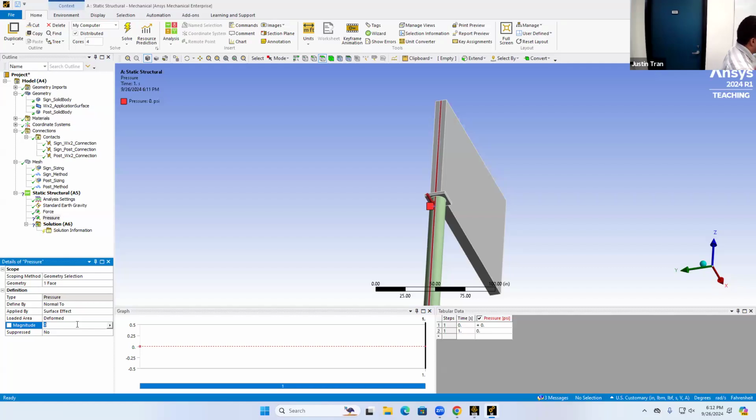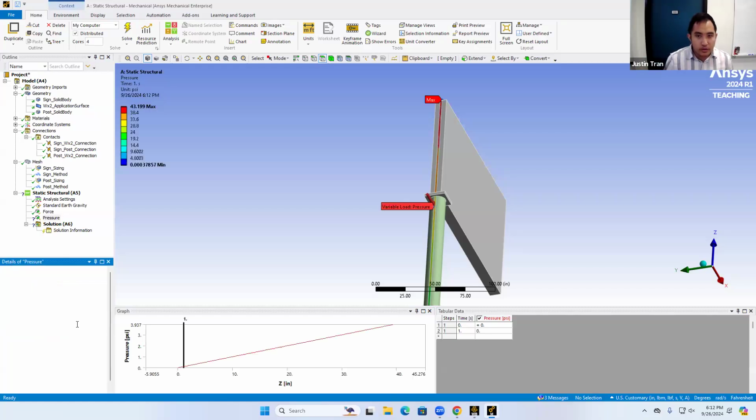To specify a spatially varying force into one of the boundary conditions here, you're going to use basically the same notation that you use to specify a formula in Excel or Google Sheets. So to specify a formula, you're going to hit equals, and then you're going to type in the function. The function that we're going to specify is 0.1 multiplied by the z coefficient. We're going to do 0.1 multiplied by z. Once you do that, go ahead and hit enter.